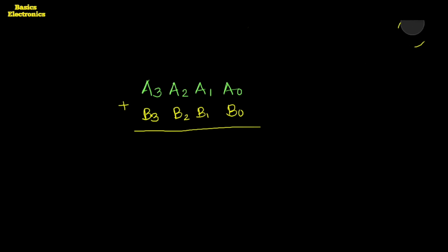Here we have seen two adders. The first adder is what we call a half adder, and this half adder performs the addition of two binary bits, not two binary numbers. It is a half adder because there is no provision for adding the carry generated, or a third bit.